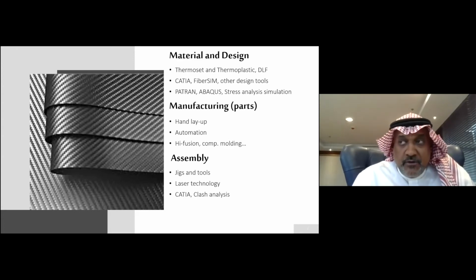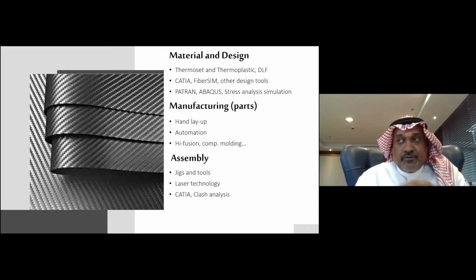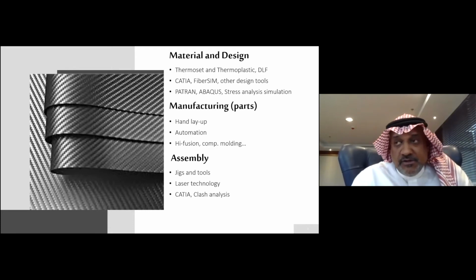Sometimes you really have to rely on, believe it or not, titanium sheets to bring out the strength of the part. So repair is not just like if you have a dent or something where you broke the fiber continuation on your part, on your structural part especially. You need to bring it back to its structural integrity. And since it's a composite part, the bigger the part, the tougher it is to repair. So at one point in time we utilized thin sheet titanium, so we can make sure the structural integrity is back. It's not just a dent where you fill it with resin and fiber and scuff it and it looks good.